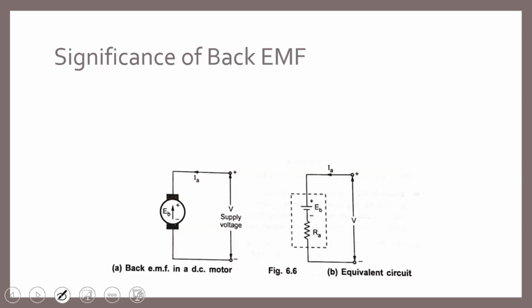Next is the significance of back EMF. Now, EMF or electromotive force, we understand this term in DC generators, wherein EMF is induced. The question here for DC motors is, is there an EMF produced in DC motors? Because it is a motor, so the output is mechanical. So what EMF? The answer is yes, there is EMF still produced for DC motors, but we call it back EMF.